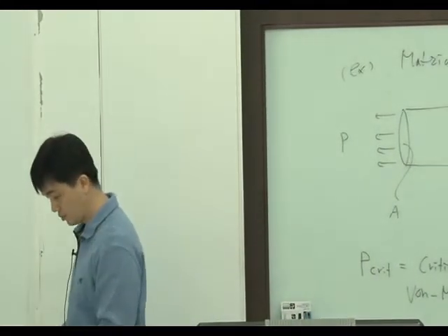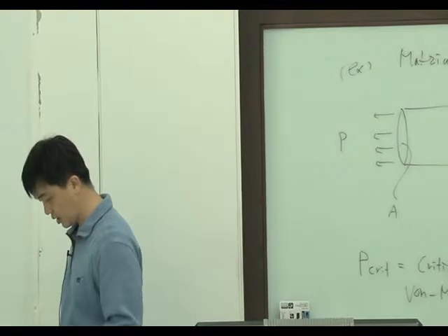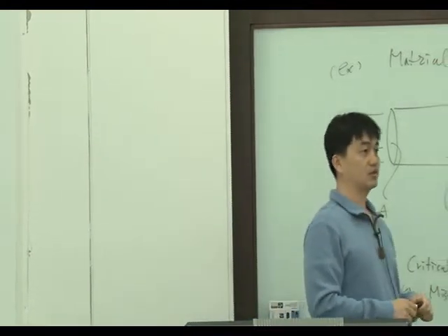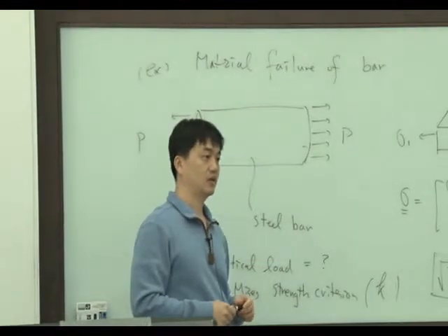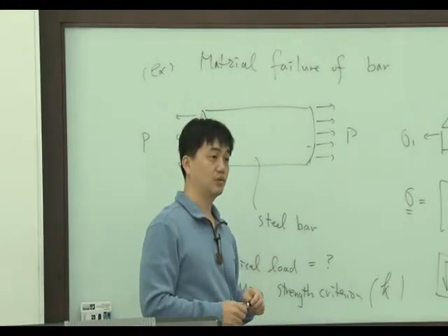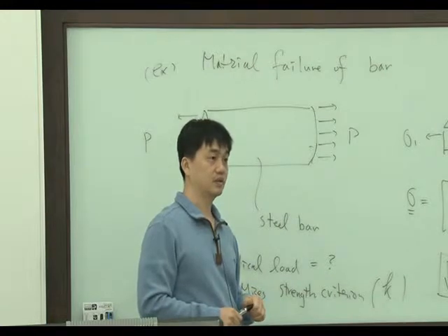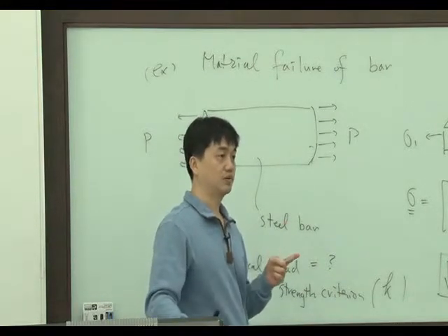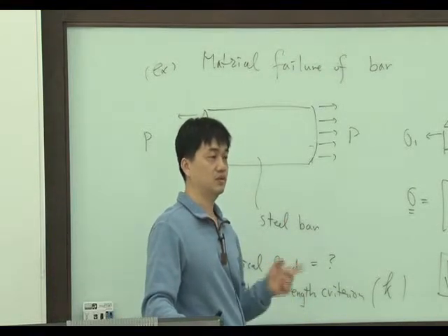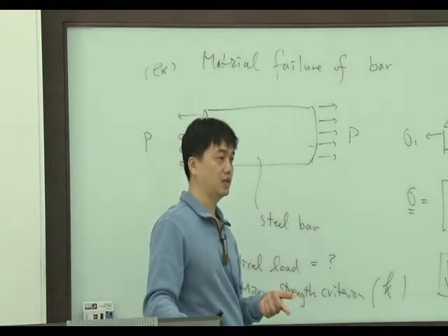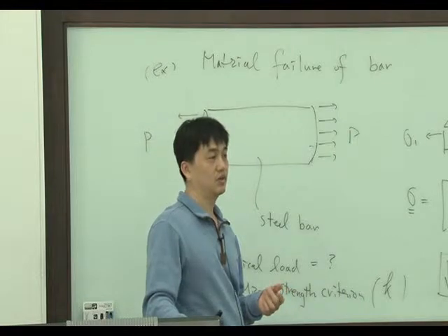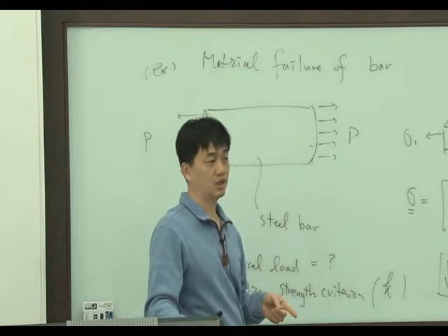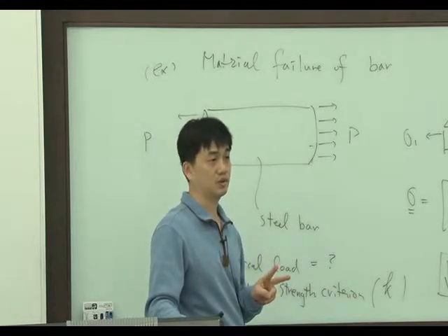So von Mises strength criteria need just one experimental test, because it has only one strength parameter. Tresca has 1, right? Tension cutoff also 1, but Mohr-Coulomb has 2 material parameters. So in the Mohr-Coulomb case, we need to do 2 experiments.